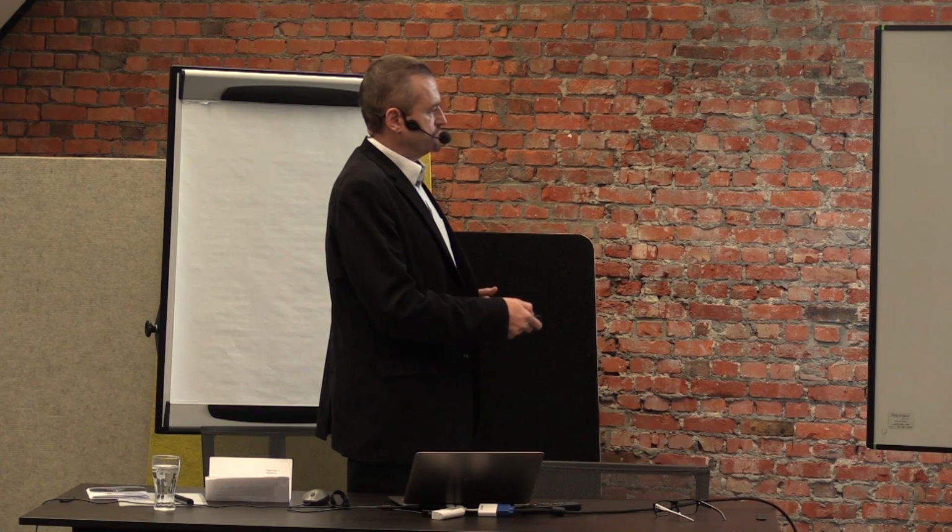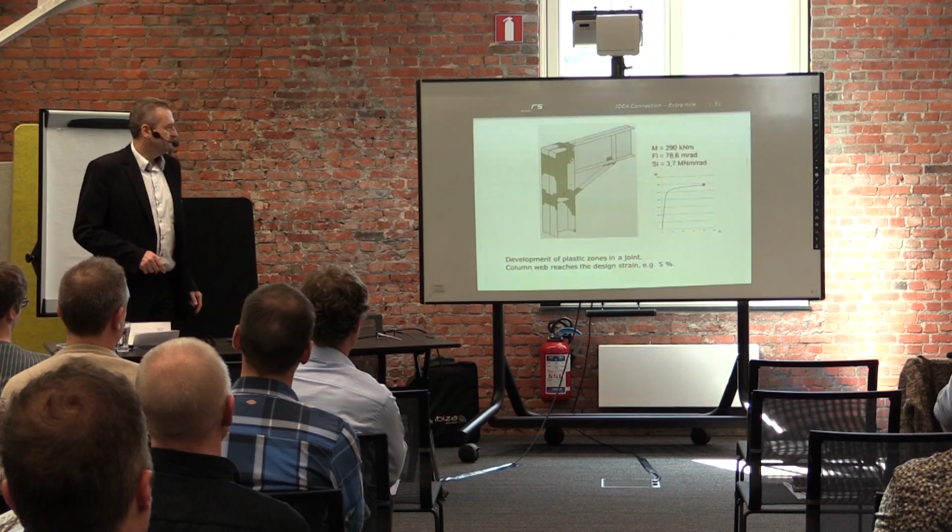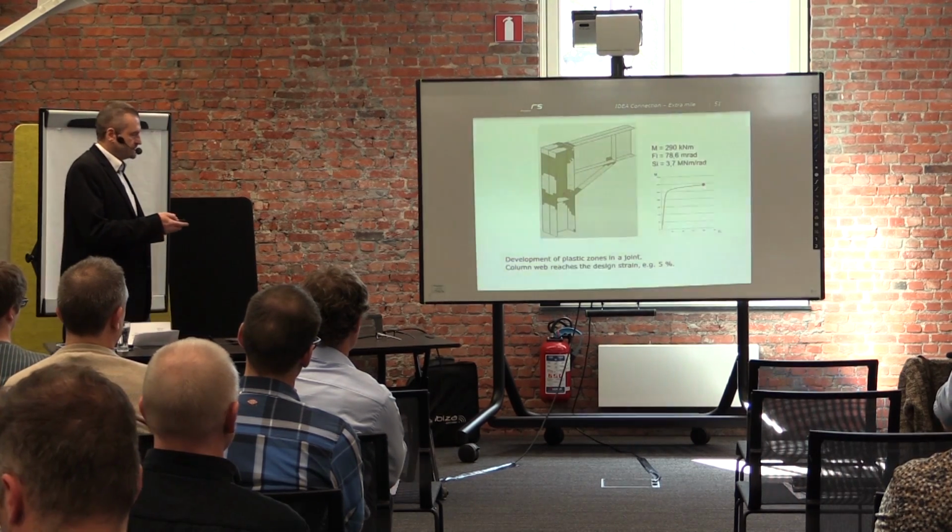At 260 the flange starts to plastify, and then you see that this branch is almost horizontal, so we add only a small load, and the plastification goes very fast. So we are at the end, because there is the first area where we are over the limit.